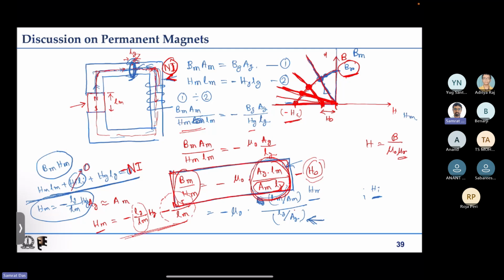Manufacturer's datasheet will provide this demagnetization characteristic. Okay, thanks. The load line is based on your application. You have to design that. So suppose if I want maximum energy from this curve, I have to operate at the center for maximum BH.